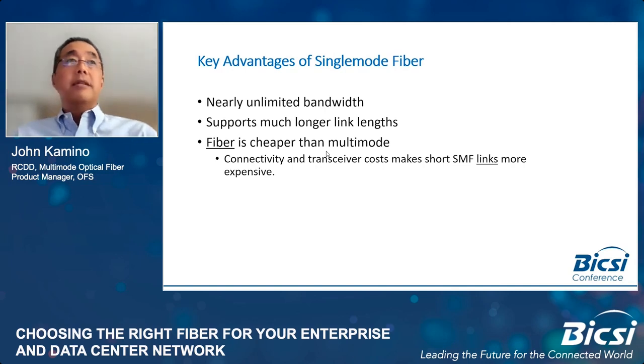The key advantages of single mode fiber are the fact that it has nearly unlimited bandwidth. From an enterprise perspective, you can almost assume that it does have unlimited bandwidth. Single mode fiber can support much longer link lengths because you're operating at higher wavelength ranges. The cable attenuation is much lower. You don't have the modal dispersion issues, so you can go much longer distances than you can with a multimode fiber.